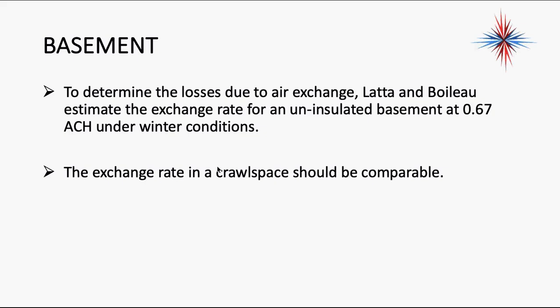Now, to determine heat losses due to air exchange, two researchers estimated the air exchange rate for an uninsulated basement at 0.67 air changes per hour. ACH is always air changes per hour under winter conditions. Again, this is a magic number that has been researched and seems to work. It's an estimate, but it works. The exchange rate in a crawl space, not a basement, but the area you crawl through under the house, is about the same: 0.67 air changes per hour. As we go through our spreadsheets, you'll see where that comes into play.